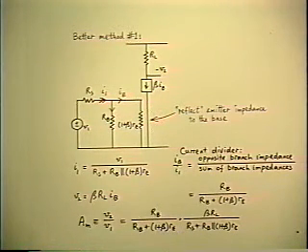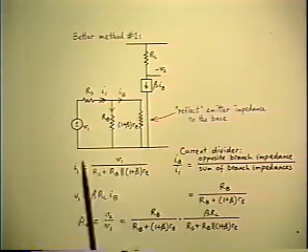And another way to say that, which we'll be using a number of times, is this means that all three terminal currents of the transistor always have fixed ratios. Collector to base is always beta, emitter to base is always 1 plus beta, collector to emitter is always beta over 1 plus beta, which is alpha. Fixed ratios. And the special case of that is if one of the currents is 0, all of them must be 0. We'll use that when we get to the extra element theorem. So it's that property that makes this reflection process possible.